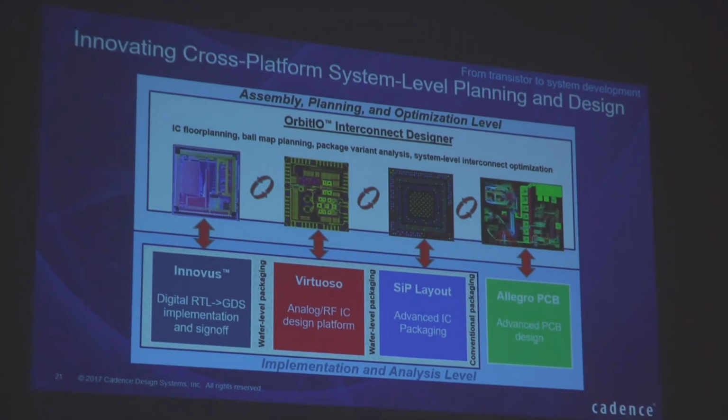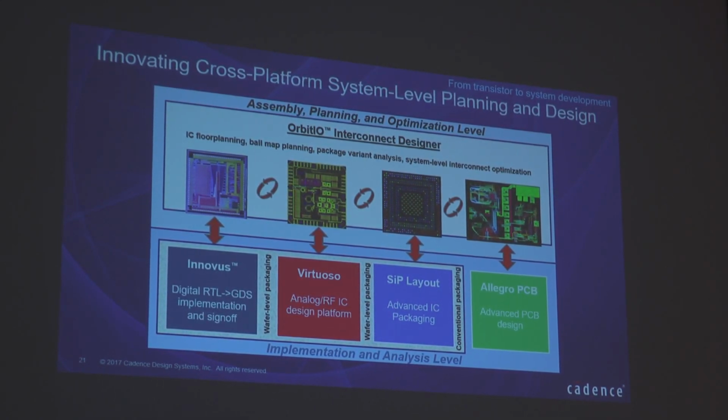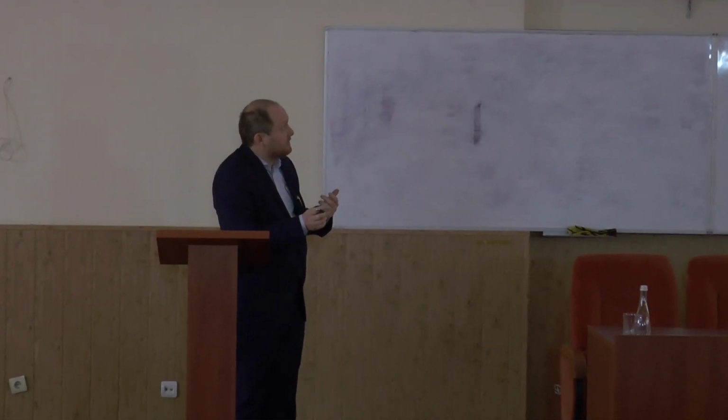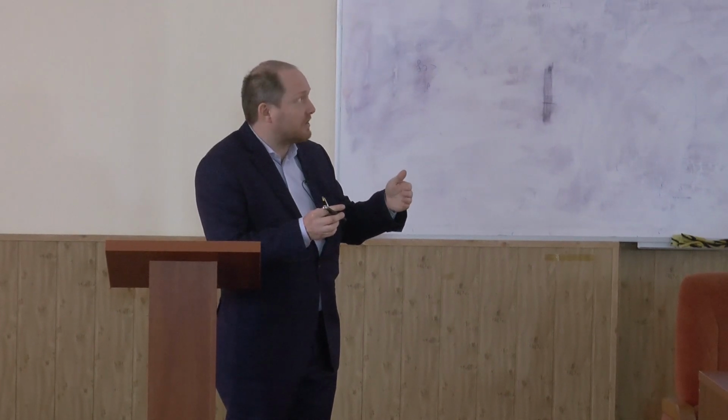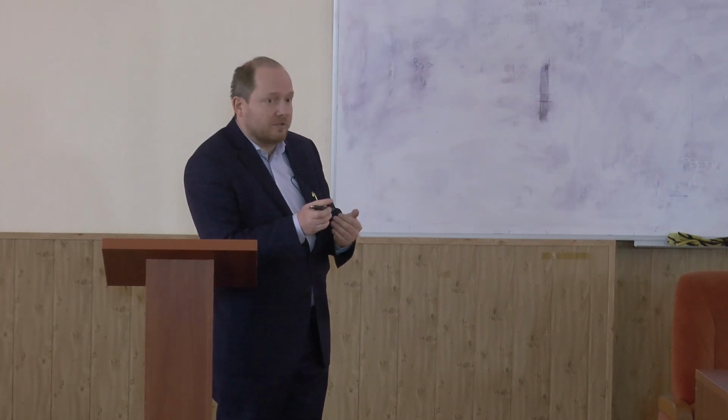If you're combining different chips on a substrate, a lot of I/O planning is necessary. You always have to make sure that all the signals are correctly routed through the substrate, that you have outputs from different tools, from your digital implementation tool, from your analog implementation tool, then from third parties, like the tool where you develop silicon photonics or MEMS, and then plan all the I/Os and how they're connected with each other.